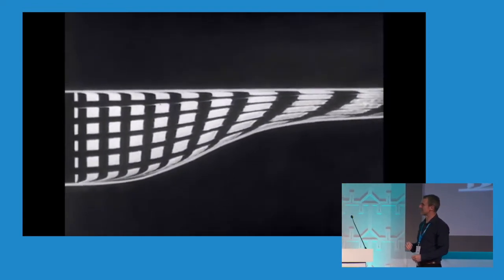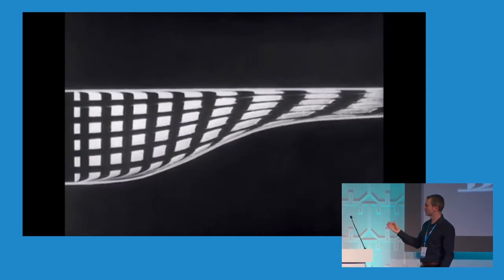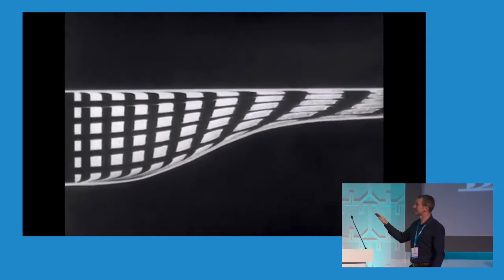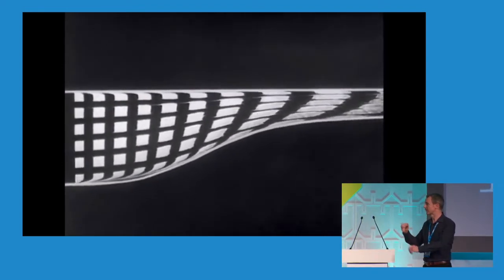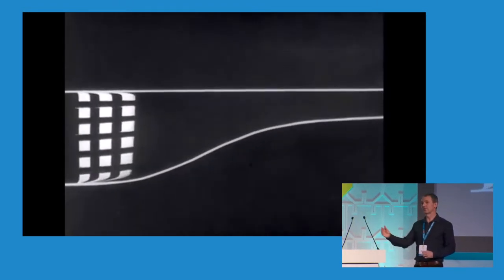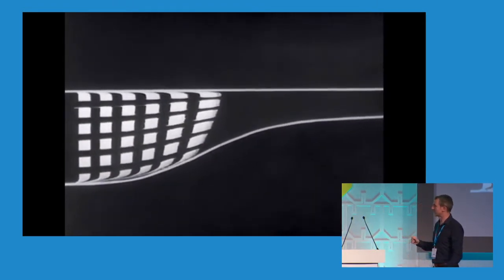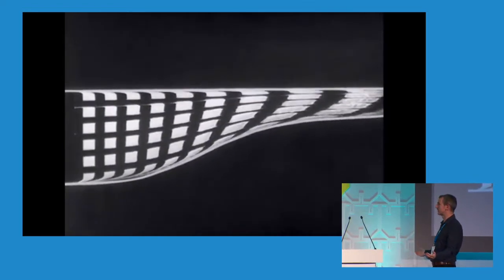But it's compounded in that when you accelerate the flow, so to try and maintain the same flow rate, so the amount of flow going through a certain pipe, when you make that cross-sectional area smaller, you have to speed that flow up. And you can see that's exactly what's happening here, which exacerbates those losses even more, which is why you get such a massive difference between the two.